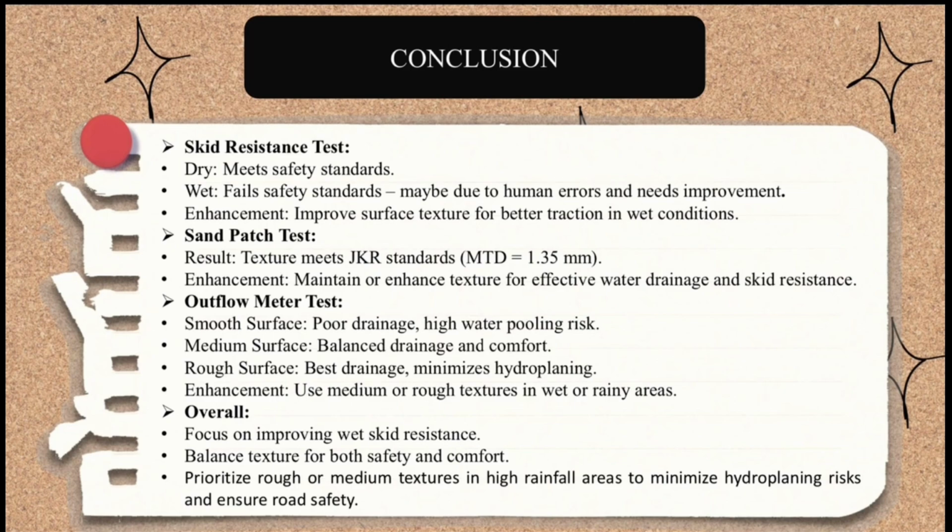Next, for the conclusion of the skid resistance test, the dry skid resistance test meets safety standards, meanwhile, the wet skid resistance test fails safety standards. This is due to human errors and needs improvements. So the enhancement that can be made from this experiment is to improve the surface texture for better traction in wet conditions. For the sand patch test, it can be concluded that the texture meets JKR standards, which is MTD equal to 1.35 mm.